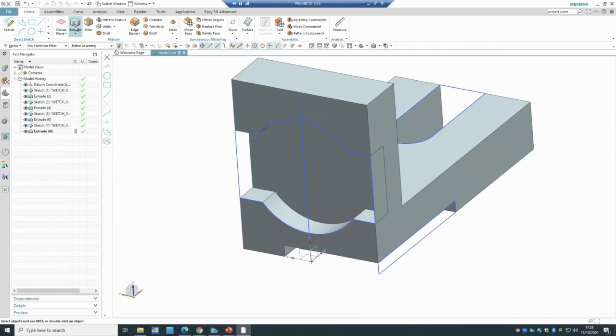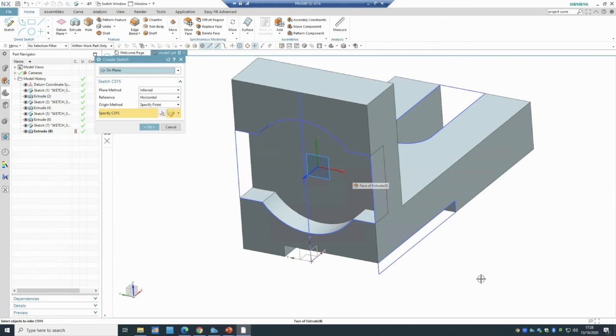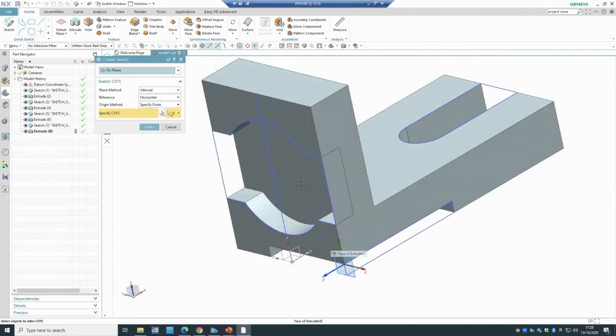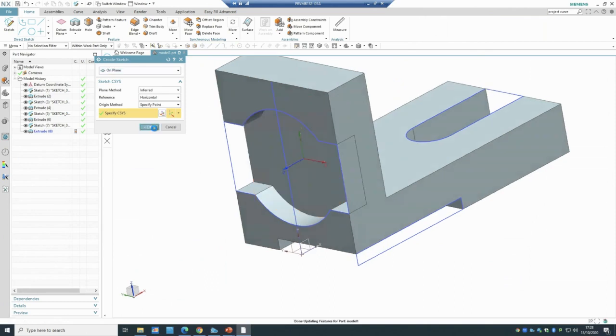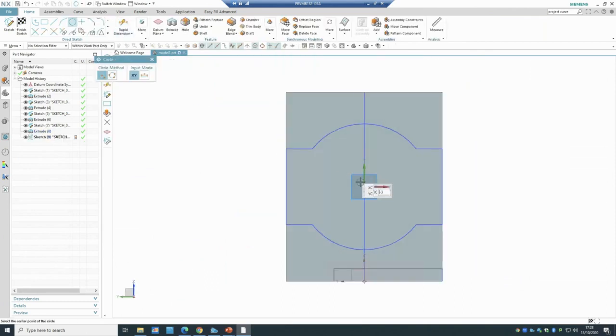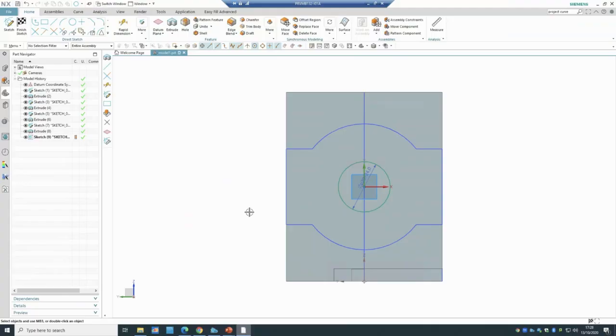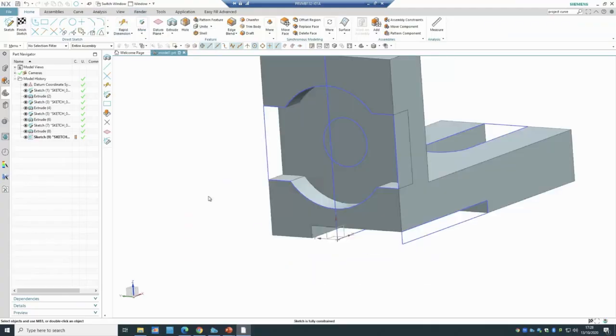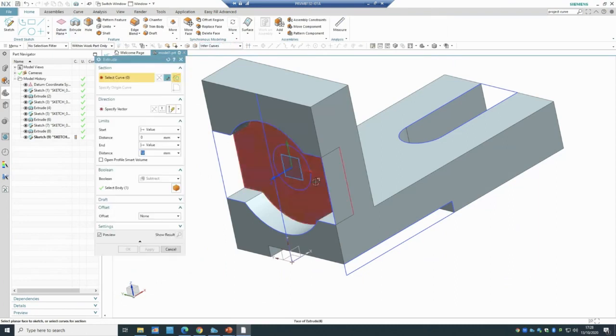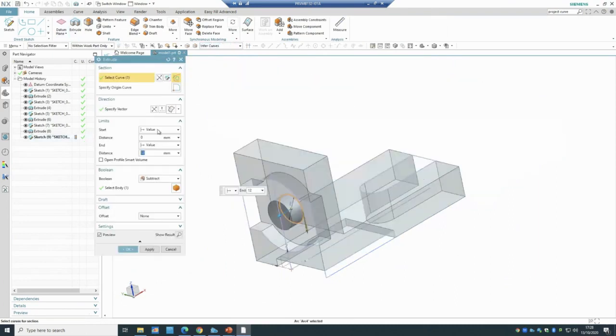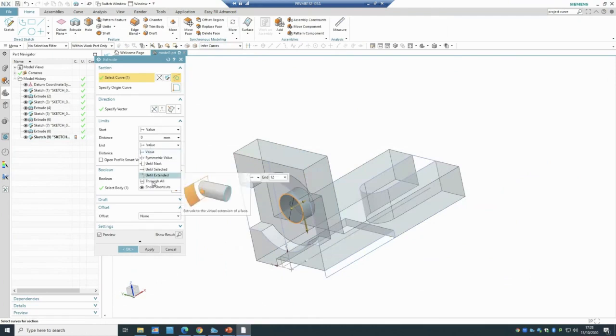And once you do that, then you go to the sketch again one more time. But this time you use this plane. So this is what I was saying is really important. The first time we use that plane, but now you're going to use this plane. Click OK. So what I have is just a normal circle that you want to do a cut there. And I think it was 24, but let me check the diameter. Yeah, it's 24, and it's the extrude, cut, or subtract, and it's true all. Pick this one, other directions, and I will change it to true all, and that's it.